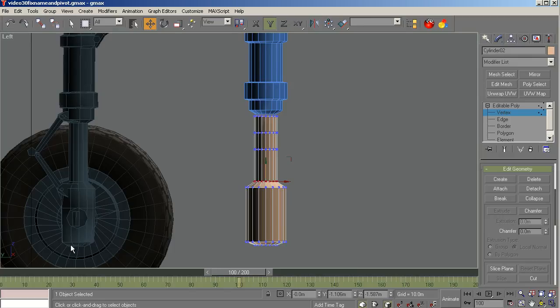So we've got this part and we've got this part, and that's really all we need. So let's just kill those and just pull these up in here. Now our gear is fully extended at 100, as you can see, and then it starts rotating back. So at 100, that's as long as it's going to be. So this part here only needs to be as long as it hides up in here on its full extension. You're good to go.